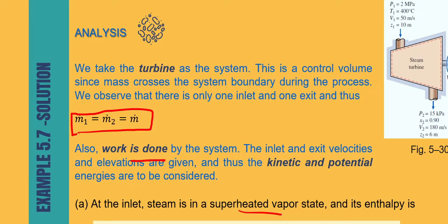If you look at P1 equal to 2 MPa, open table A6. Can you open table A6? What is the value of T saturated? Can you check? Okay, so at P equal to 2 MPa, the saturated temperature is equal to 202.38.